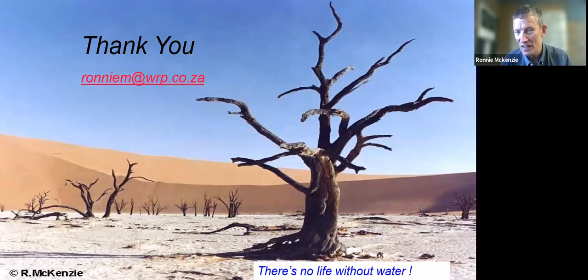If you don't have much leakage in a zone and you're not getting many pipe breaks, then leave it alone. Don't fix something that's not broken. But if you find a specific area that's experiencing a high number of pipe breaks on a regular basis, then by all means, stick in a small PRV for that zone. It can be 1,000 connections or 500 or 10,000.